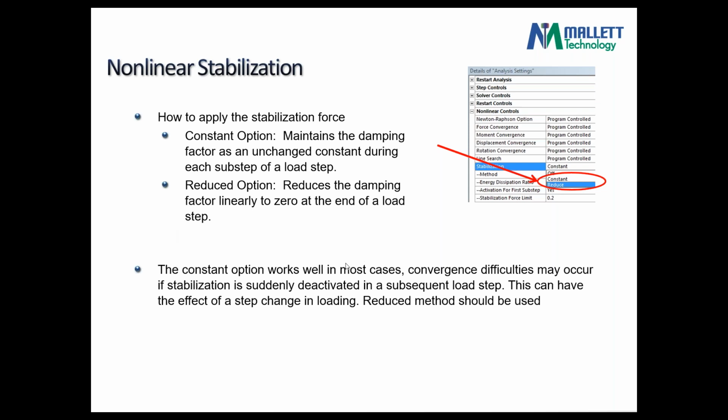In many applications, and the one I showed you, a constant value is not bad. However, one thing you want to watch for: in any nonlinear analysis, you cannot allow things to happen instantly. You might encounter difficulties if you apply it suddenly, immediately, or you take it away. So you've got to be careful with that. If that's the case, then you probably want to go back to the reduced method. So ideally, in any application, in fact for all nonlinear analysis, when you apply loads or features in an instant fashion, it causes instability in the solver and things go haywire.